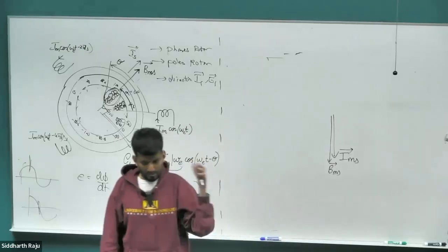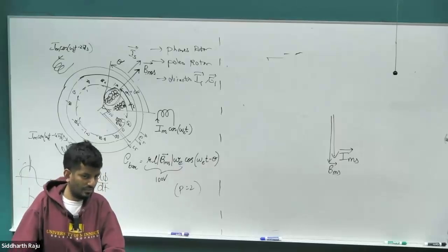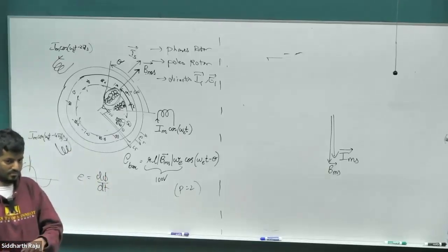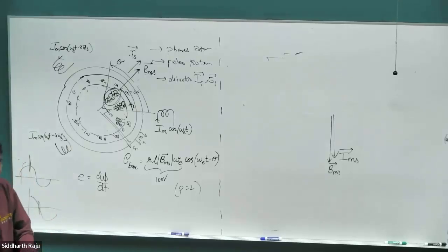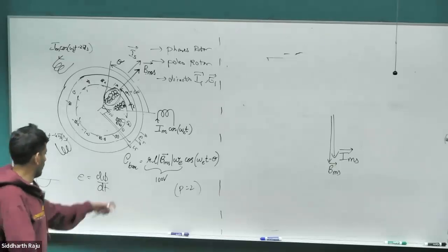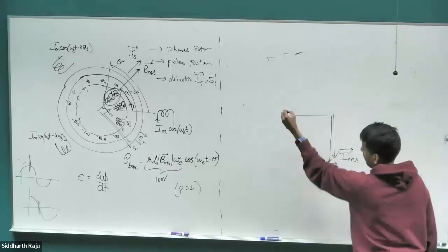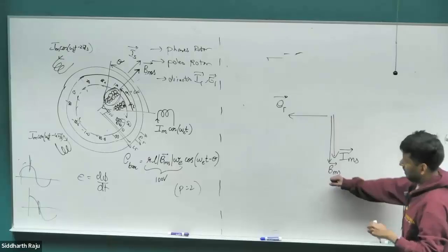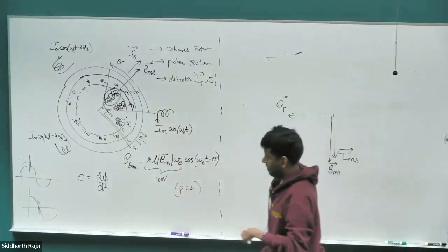Where is the rotor voltage phase vector going to be? We already saw this. So let me ask you the other question. Where is the rotor current phase vector going to be? Anybody? 90 degrees behind, right? 90 degrees behind. Right there, the drawing that we did there. So the induced EMF on the rotor is going to be 90 degrees behind from the magnetic field that caused the voltage in the first place.